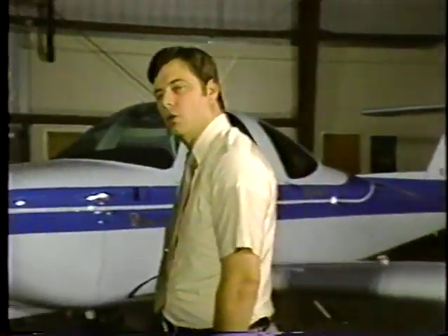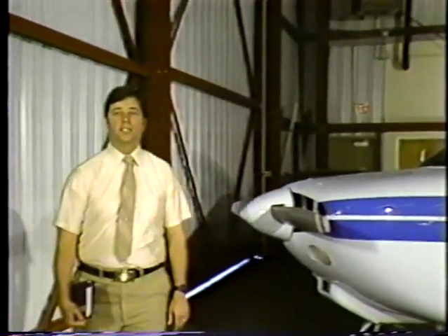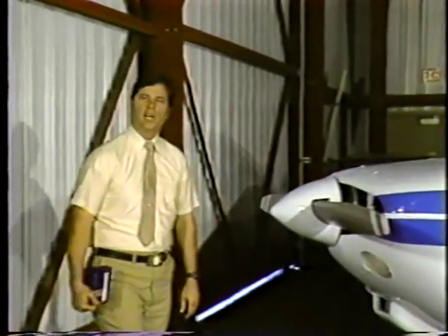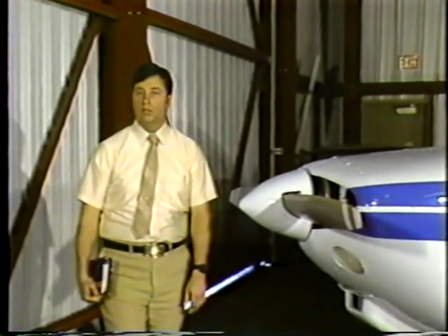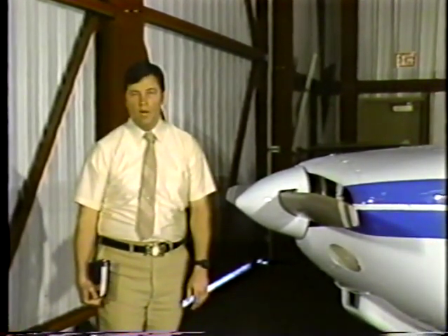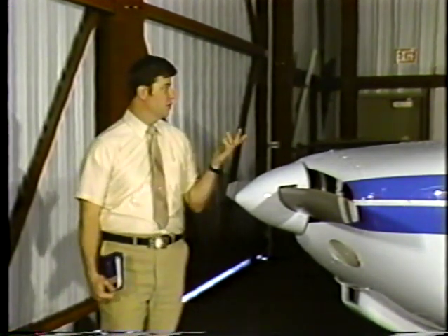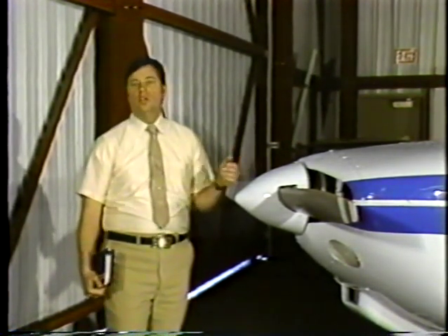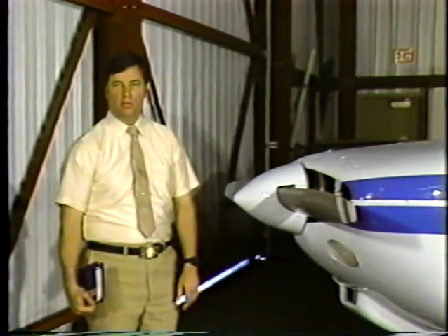The pilot is responsible for ensuring that the airplane is properly loaded and remains within the center of gravity limits established for the airplane. To assist the pilot in his determination of the center of gravity location or balance point, the designer provides a reference point from which to measure the location of the various weights loaded on the airplane. The point is called the datum or datum line.